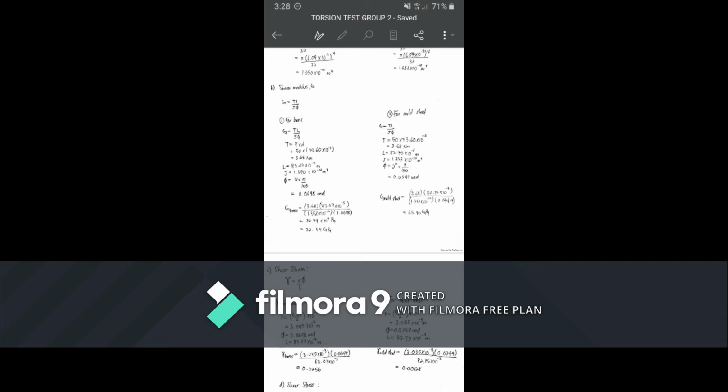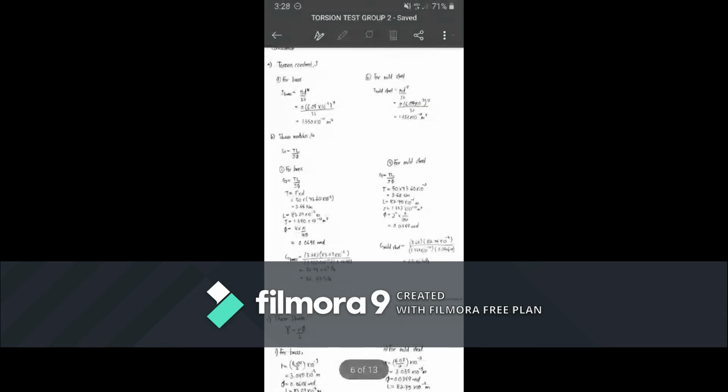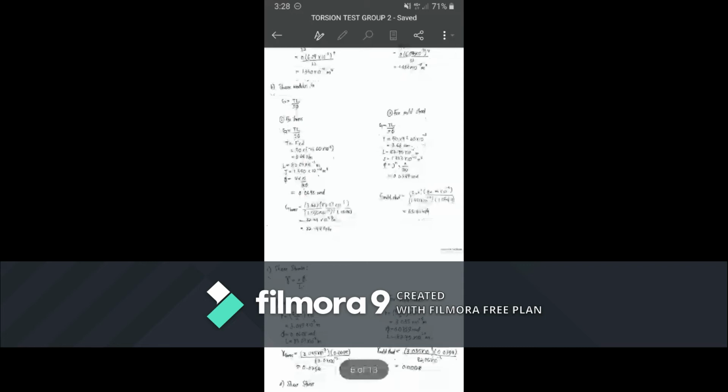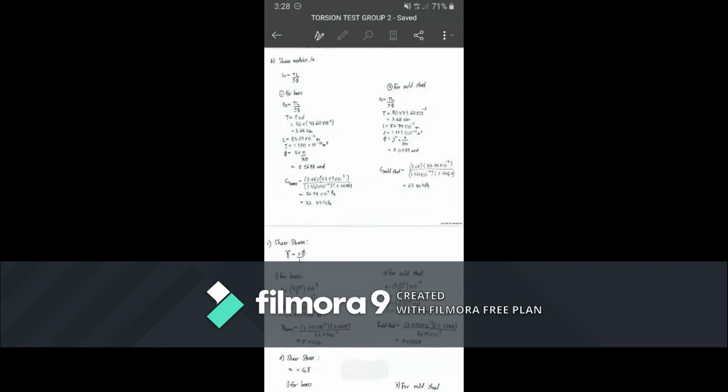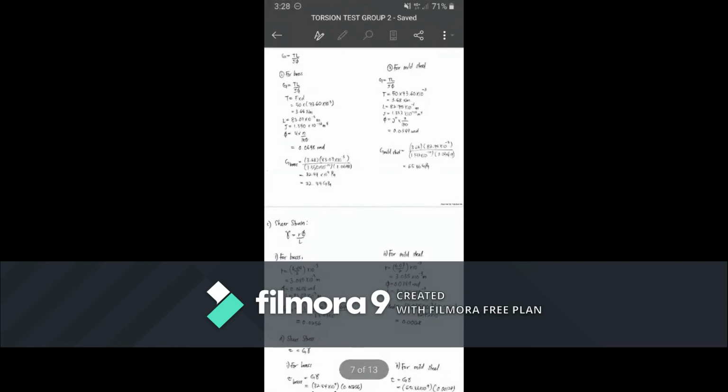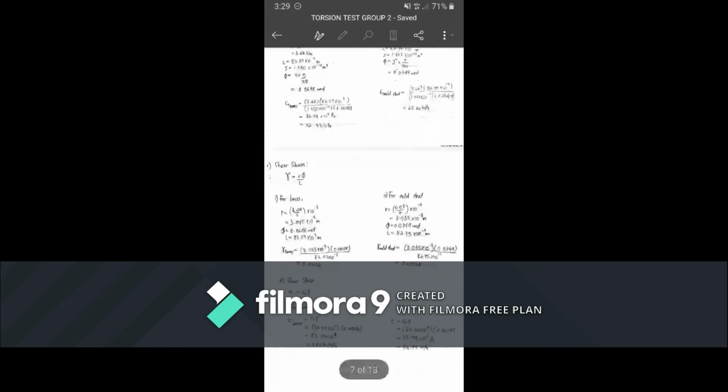For mild steel, we'll also need to find the torque, that is 50 Newton times the distance. We will get the torque, the length is given, and J we will get from the above calculation, and the angle of twist we need to find in radians. After we get those values, we insert them in the formula, and last we will get the answer.